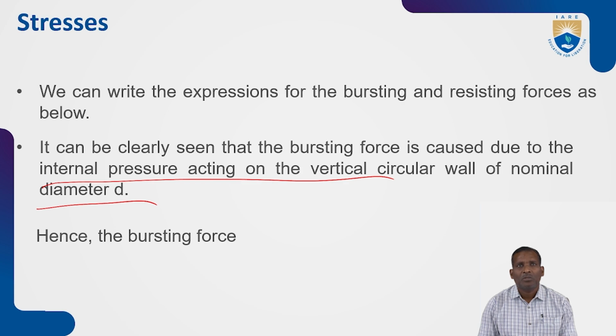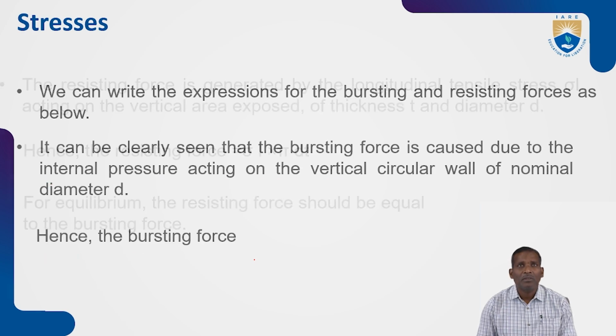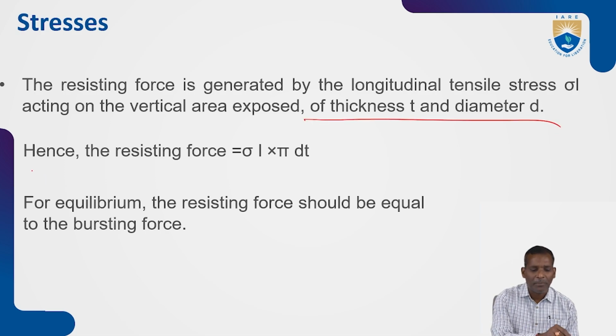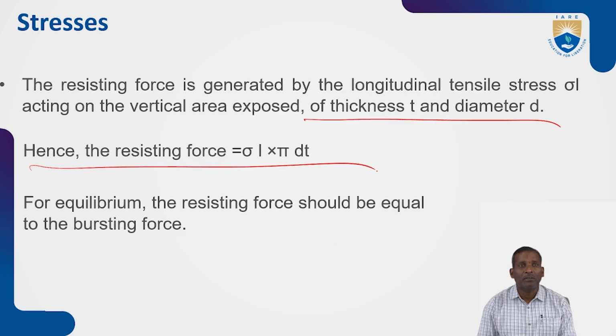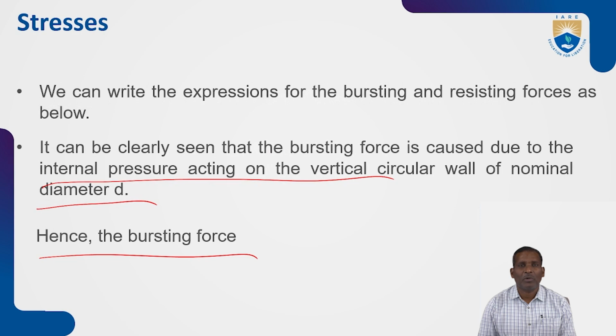Clear? So the bursting force we need to calculate. The resisting force is generated by the longitudinal tensile stress acting on the vertical area exposed, with thickness t and diameter d. So the resisting force you can calculate, and then for equilibrium the resisting force should be equal to the bursting force. So what is the bursting force here?